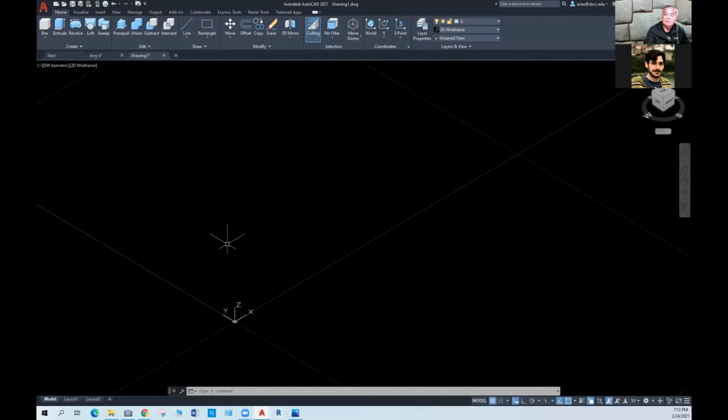And so, for example, I'm going to insert a view here. How do I, and you are all experts on this now, how can I bring in here a drawing that I previously have done, that I have somewhere in my computer? Well, I can do it many ways, right? I can do an XREF, I can do a block, and I can do copy and paste. Those are 3 ways to combine multiple drawings into other drawings. And so maybe I do that.